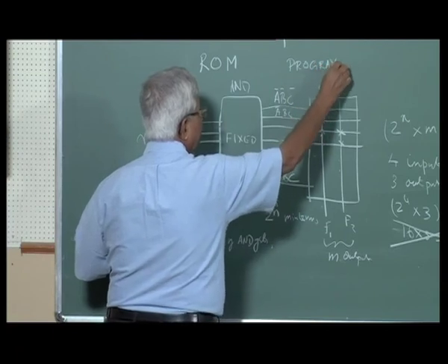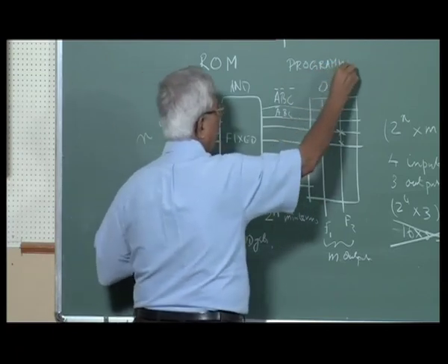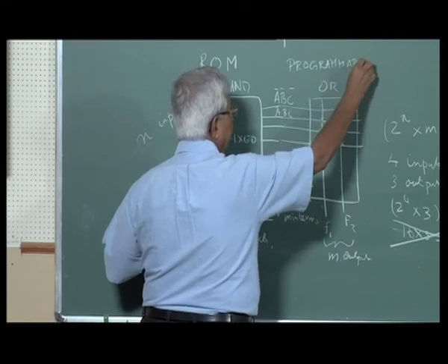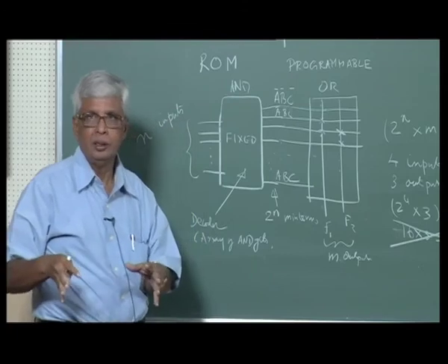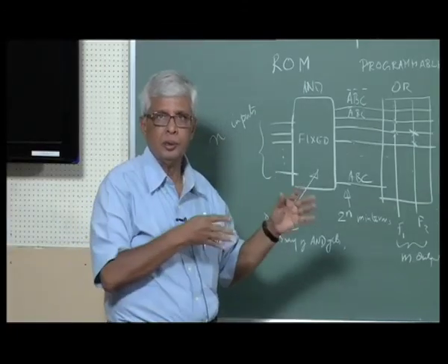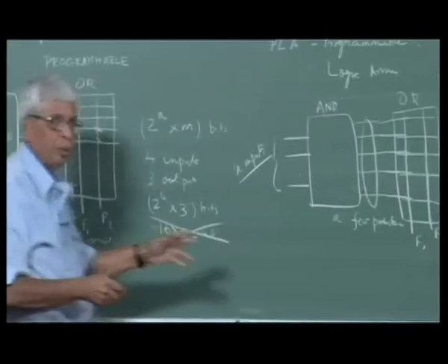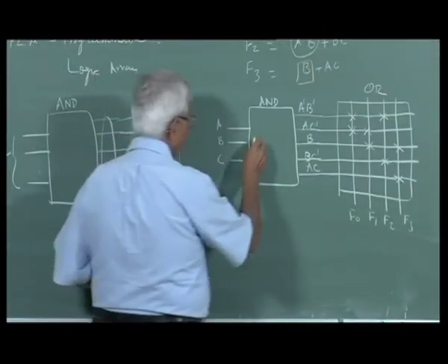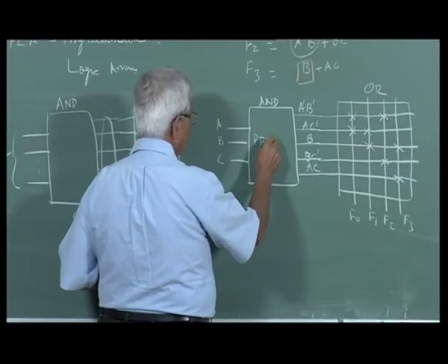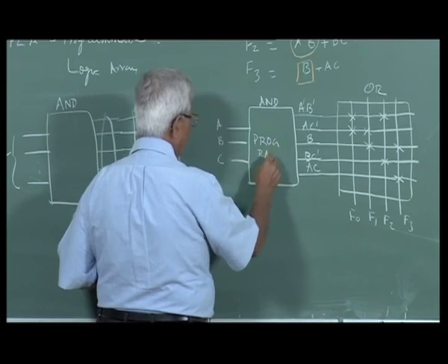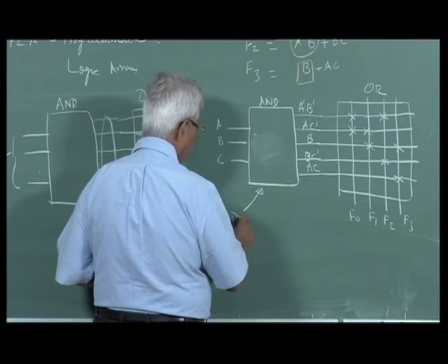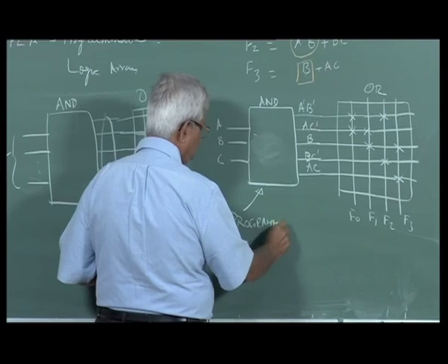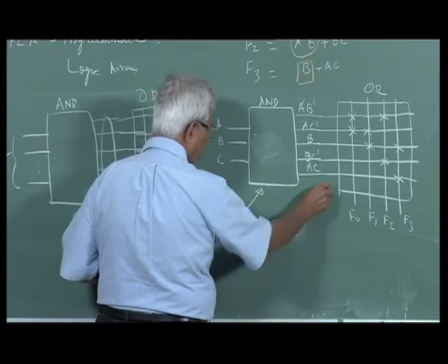Why is it called fixed? Because all the minterms are generated, whether you want it or not. Whether you like it or not, all the minterms will be generated. Here, I can program this. And also this, both are programmable.